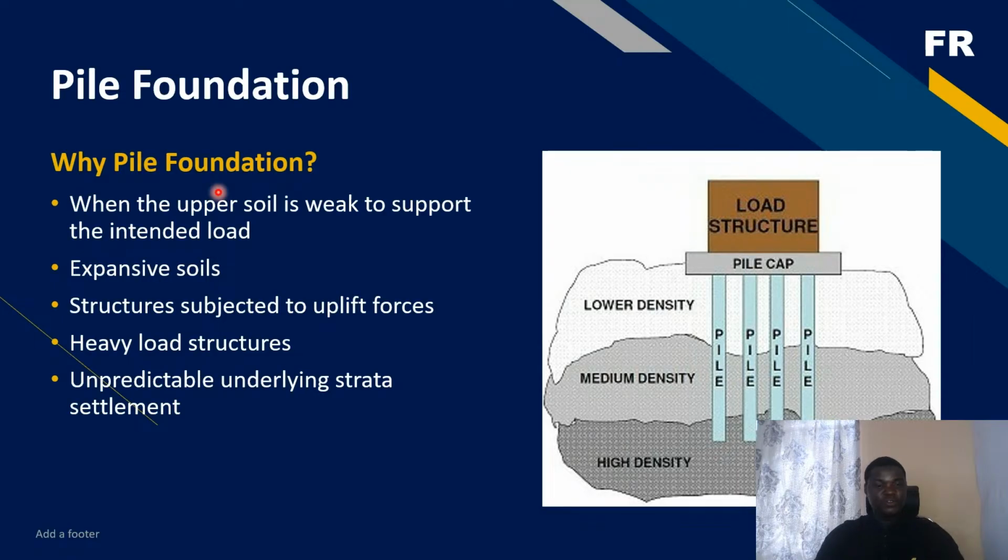The first of them is when the upper soil is too weak to support the intended load. This is a typical example of when the load coming on the foundation or on the soil is much higher compared to the capacity that the soil can bear. In that kind of situation, you might tend to go for a deep foundation, in this case, pile foundation.